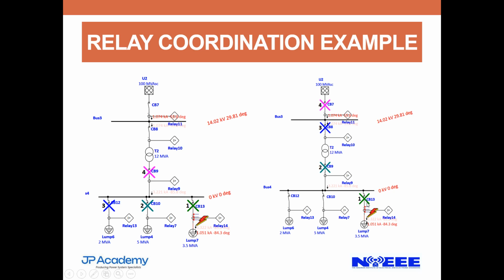Now, when we talked about relays, we said reliability, the certainty that the relay will operate as and when due. When we come to relay coordination, we are saying that assuming one of the relays does not have the complete qualities required, assuming its reliability is low, assuming the relay does not operate as and when required, we need a backup.